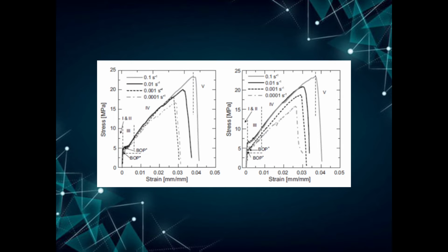of TRC with plain matrix and for TRC with the matrix reinforced by short glass fiber. From a macroscopic perspective, the bend over point (BOP) of each of the curves corresponds to the formation of a first matrix crack crossing the entire cross-section. 5 distinct zones are identified using Roman numerals, with 2 zones prior and 3 zones after the bend over point